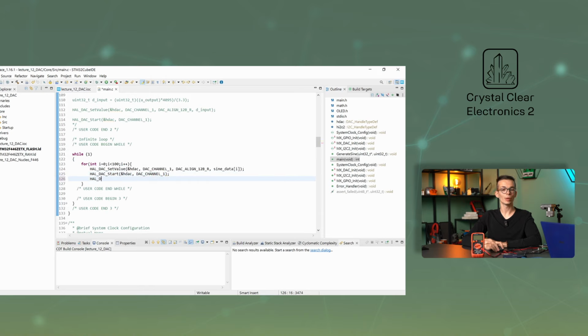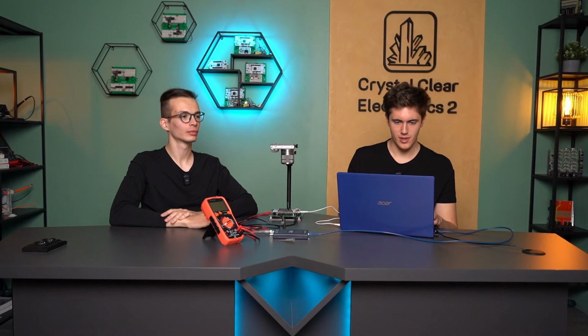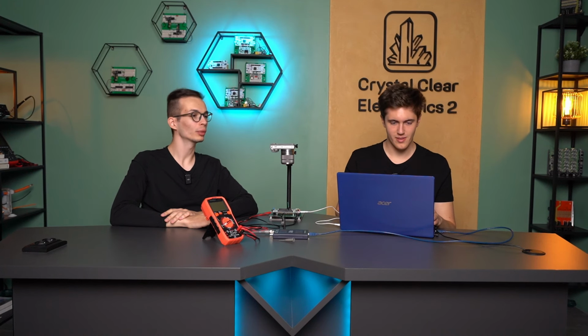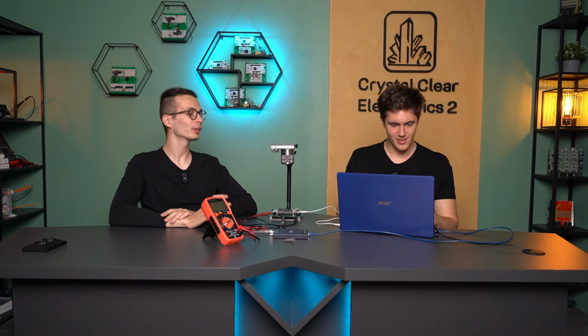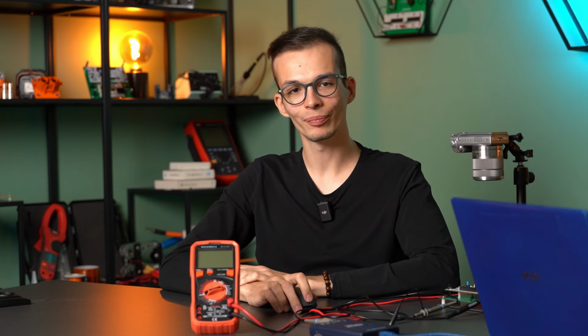Then the HAL_Delay 0 is called. Delay 0? We will wait 0 milliseconds? Yes, exactly. HAL_Delay 0. But does it make any sense? Yes, it's good that you asked that because there's a twist. We will wait 1 millisecond, but still write 0. To find out why this is the case, we need to understand the operation of the HAL_Delay function. Until then, please compile the program and upload it to the controller.